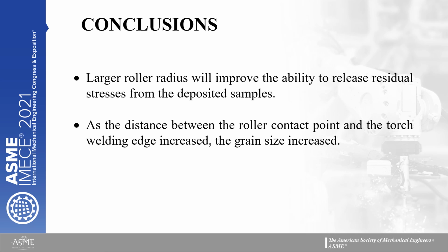Larger roller radius will improve the ability to release residual stresses from the deposited sample. As the distance between the roller contact point and the torch welding edge increased, the grain size increased as well.